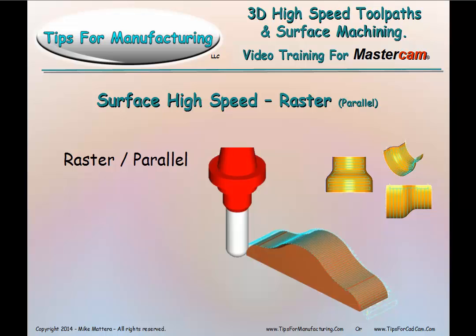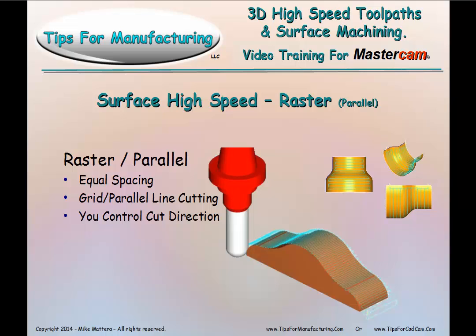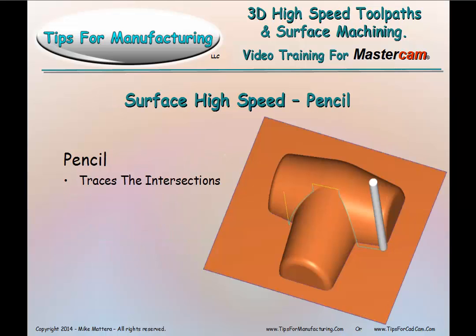This is raster. You might also refer to this as parallel. It's an equal space cutting. It works on a grid or a parallel line cutting. You control the cut direction. It has high-speed transition capability, and you have boundary control. Pencil traces the intersections. It's used to clean the corners between surfaces.